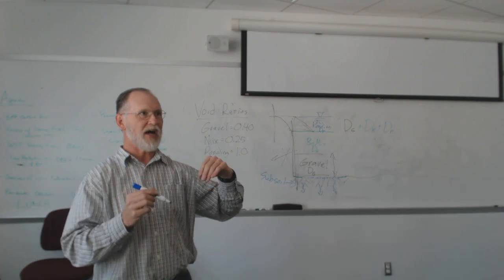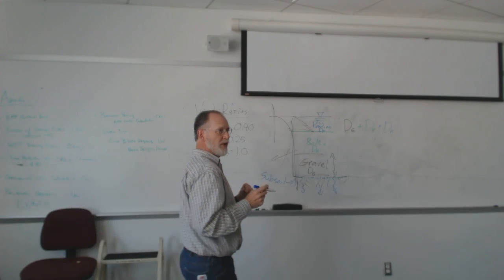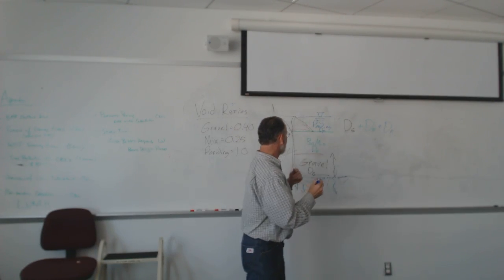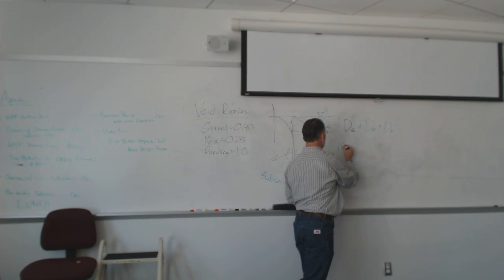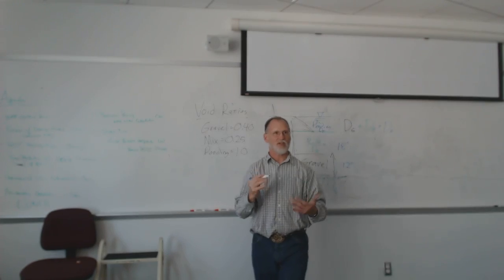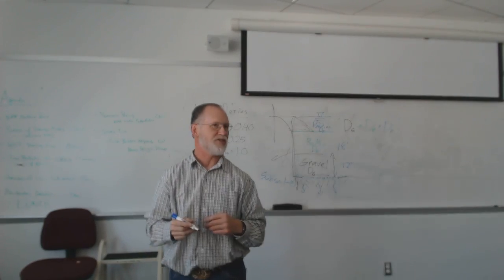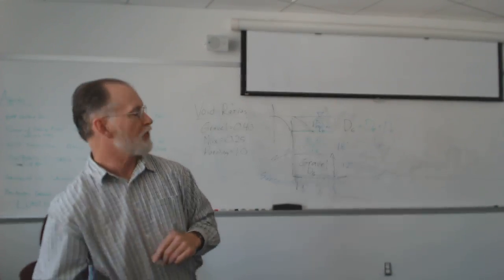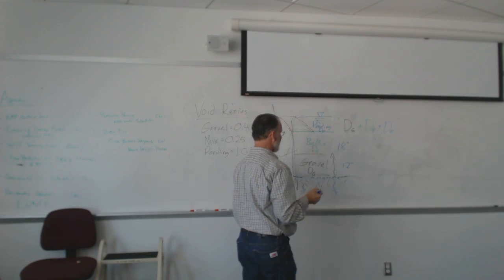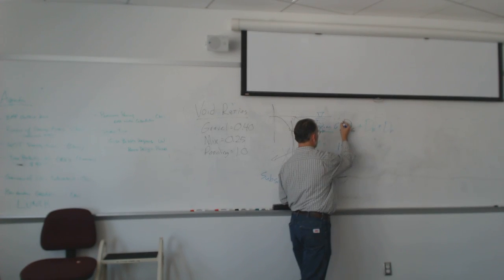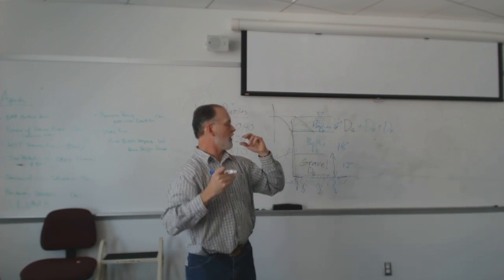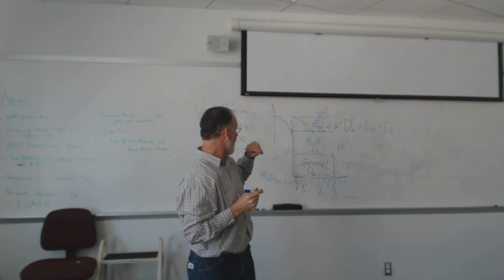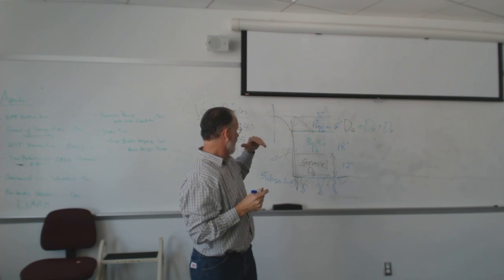You can assume some depths and say, I'm going to start with 12 inches of gravel. 18 inches of biomix, since 18 to 24 inches is a pretty common minimum in most localities. Ponding depth, 6 inches.